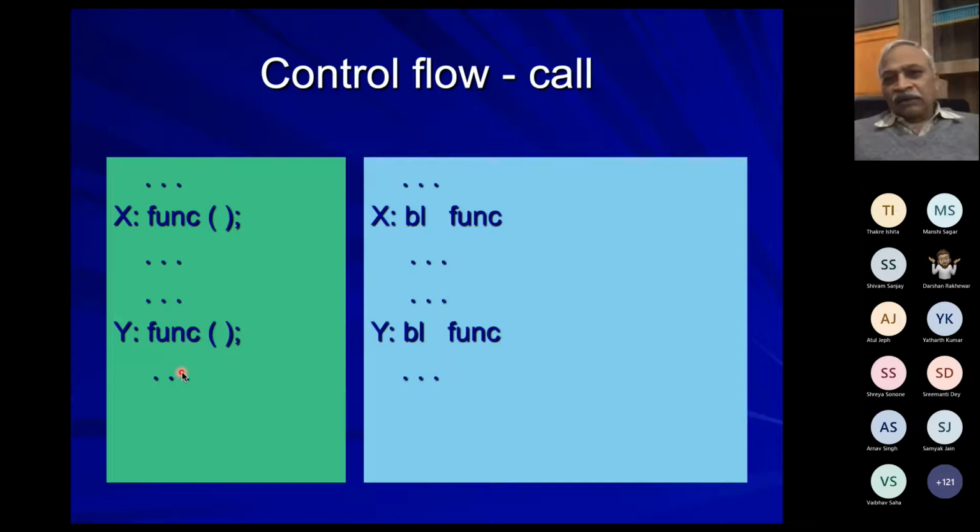The instruction which you have in ARM is BL for this purpose, which is an abbreviation of branch and link. Link is referring to the place where you are returning. So you are not simply branching, but you are remembering from where you are coming, and that information needs to be stored somewhere. BL is a variation of branch instruction, but the additional job you need to do is to remember from where the call was made.